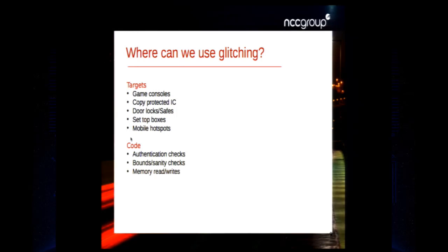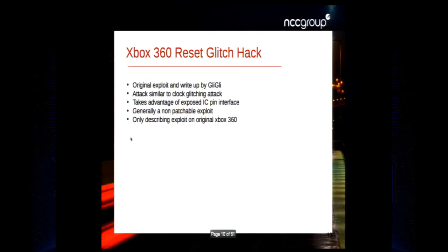Something you can also target are memory reads and writes, which can yield some interesting results depending on what you do. So now we're going to go over the reset glitch hack that was done by Gitch. And this is really similar to a clock glitching attack.